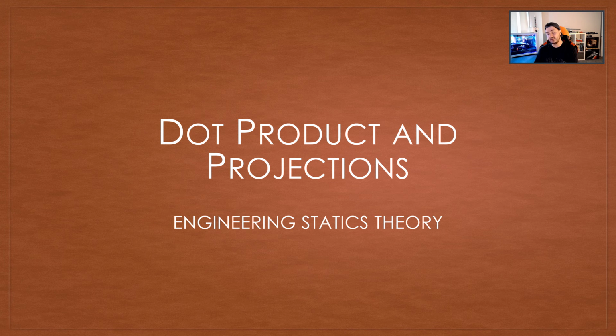Typically, at the University of Alberta anyway, the first midterm question is what we're doing here in this second week. It's going to be 3D Cartesian vectors. Now, the first part of the midterm is going to be focused on that resultant force, or the first part of the question, finding the resultant force. In the previous two videos, we said that's no problem. We can find those resultant forces. Now, the second half of that first question is going to be related to this, dot product and projections. So let's discuss what those are.